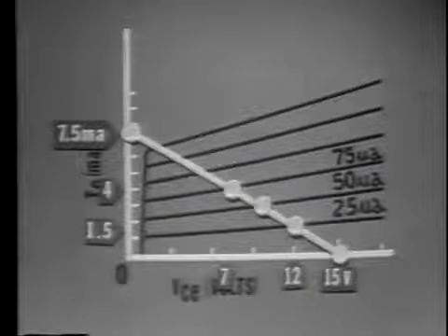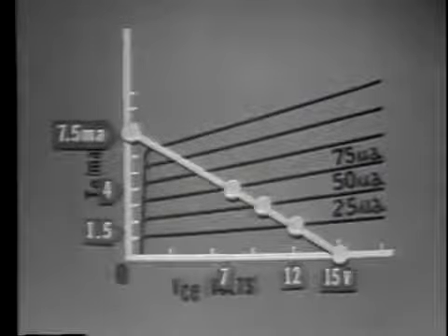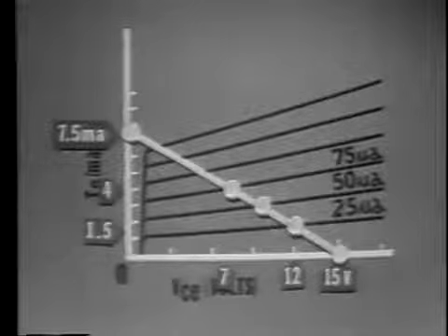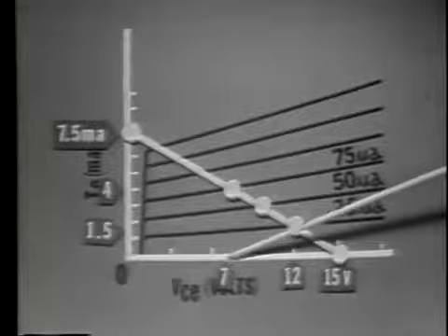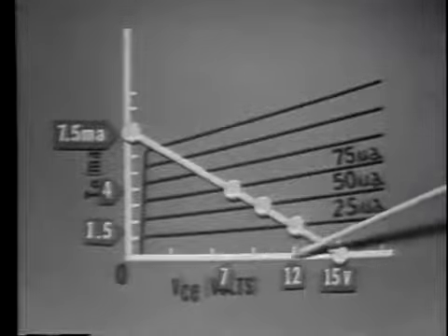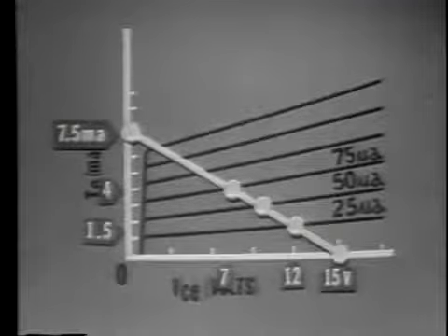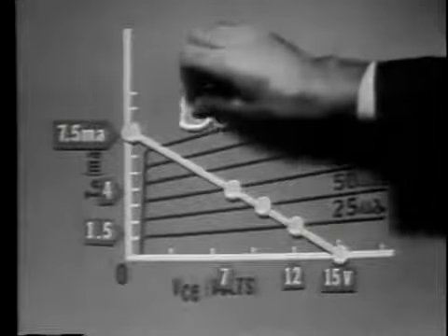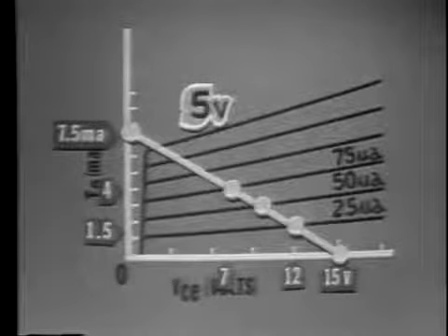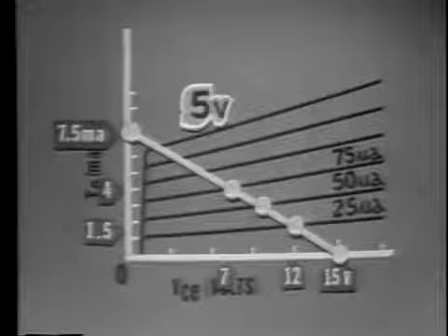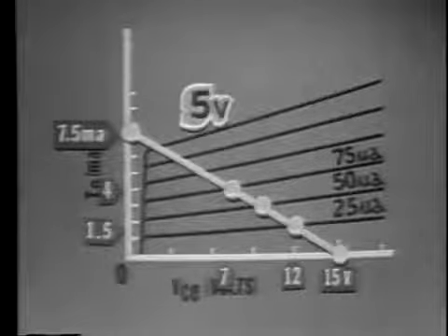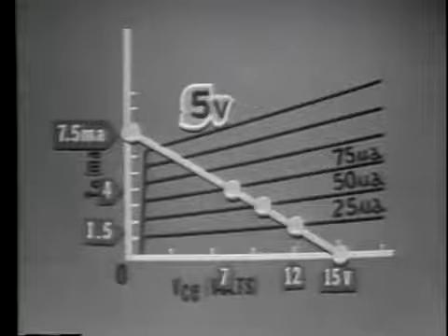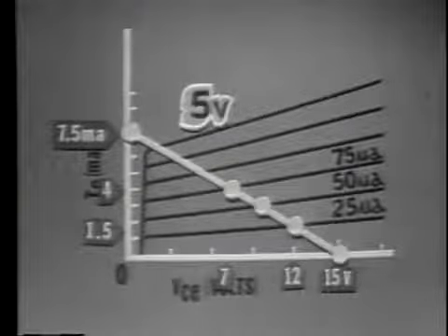At the same time current changed, the graph indicates a collector voltage change from 7 volts to 12 volts, or a total of 5 volts peak to peak. Okay, we have a 5 volt peak to peak change in the output, but what was the input voltage change? Remember we said earlier the base to emitter resistance was 4K ohm.